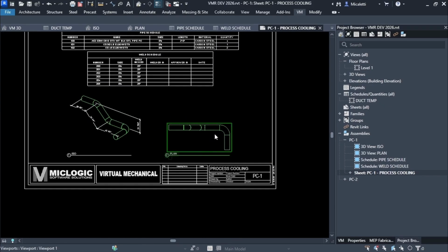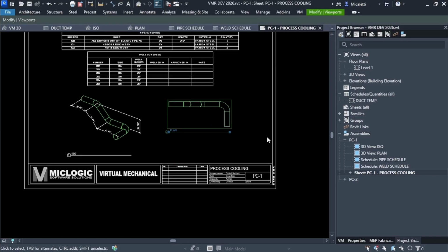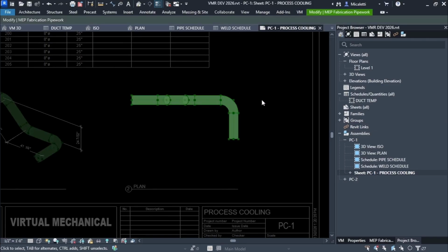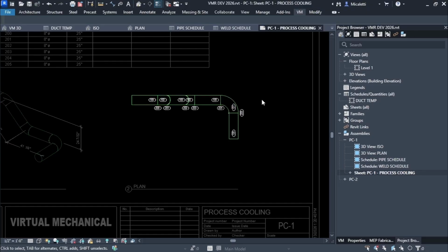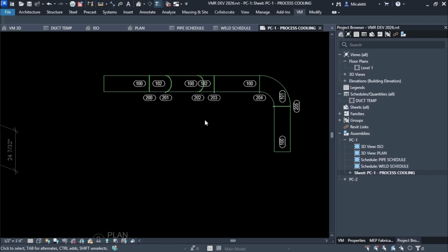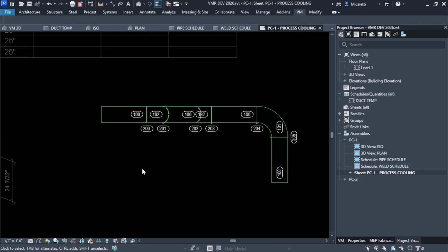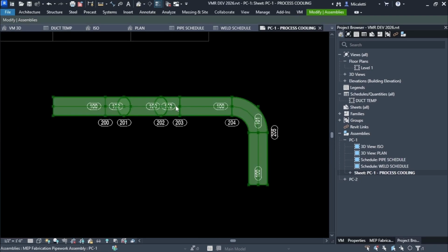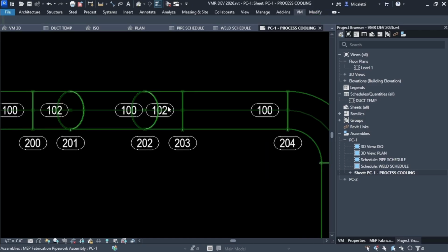And then for this, out of the box, I might want to do this, right? So I'm going to double click into this view, and I'm going to tab select, and I'm going to say VNT. That's my hotkey for number tags. Now, out of the box, I have it set up this way. I want my number tags on C2 with a 2-inch offset, and that's exactly what I got. Now, if it doesn't fit, move it below, and so you can see my weld. Now that works. That's pretty much done.